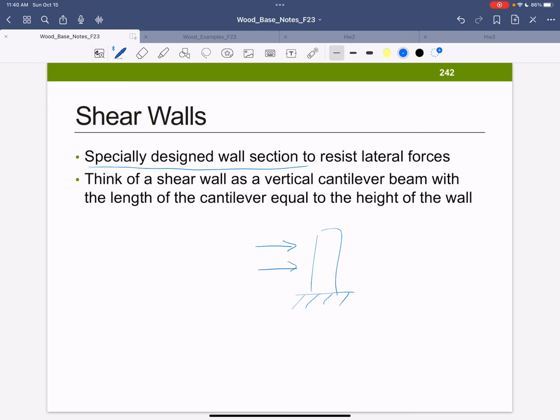It's a little easier when you think of a skyscraper in this respect, but this is what a shear wall is. The width here is relatively thin compared to the height, but this width, how wide your shear wall is, also determines how much shear it can take from the lateral load.